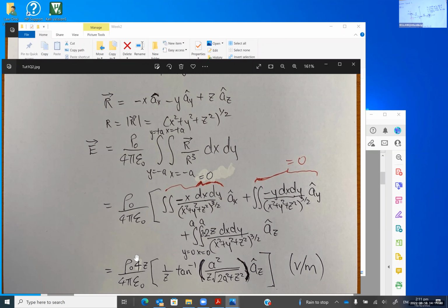Okay, so now let me ask you, what is the unit of electric field? Watt per meter. What does your FE 1007 tell you? Electric field, what's the unit? Newton per Coulomb, right? Yeah, it's from the formula F equal to QE, right? So E equal to F divided by Q. Force is in Newton, charge is in Coulomb, so Newton per Coulomb, which is equivalent to volts per meter. So for electrical engineers, we always use volt per meter. We don't use force over charge.